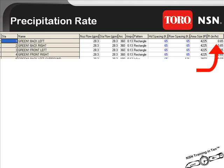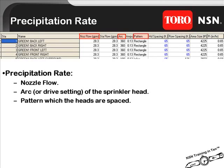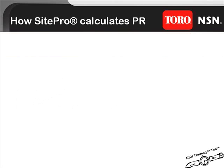To accurately calculate this rate, SitePro uses the following information: the nozzle flow, or how much water is being put down, the arc of the sprinkler, or the area in which the water is being placed, the pattern in which the heads are placed in the field, and finally, the head and row spacing at which these heads are placed. Now, the area definition and how much water is being placed there is somewhat self-explanatory. So let's focus on the pattern and spacing.